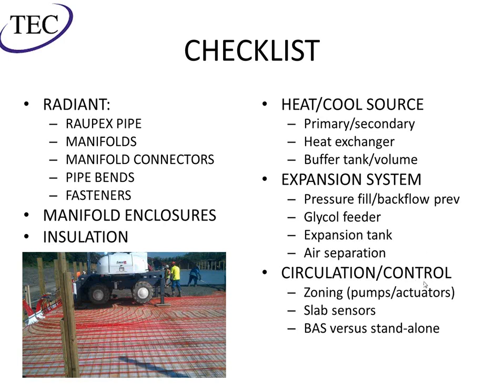And then your circulation control. We didn't get too much into zoning, but as I mentioned a couple times, you can do manifold mounted actuators. You can do an actuator for the whole manifold, or you can zone with pumps. And depending on the size of your system, that's usually the determining factor of zone pumps versus actuators. With the high efficiency variable speed pumps these days, actuators are making more and more sense just for energy's sake.